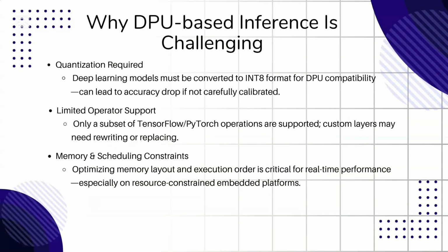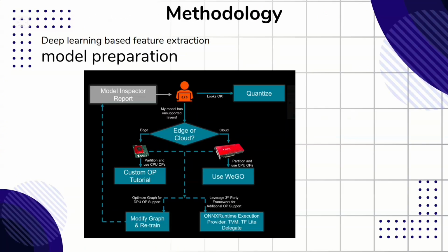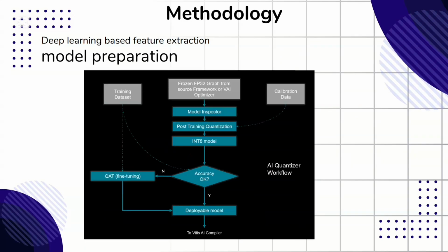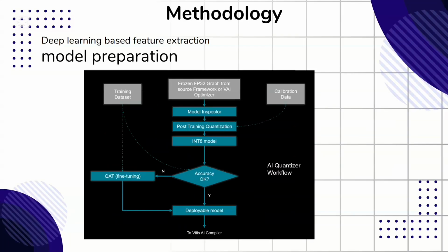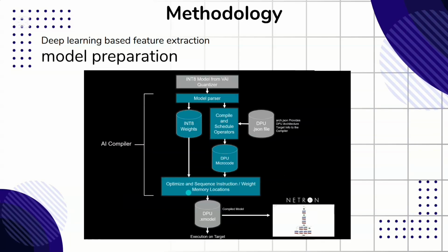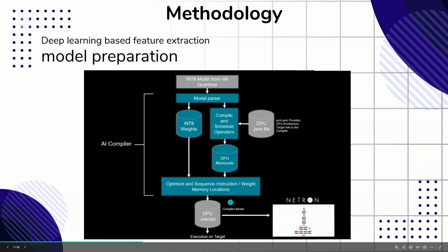With it, we compile our learned model into a deployable format called an xmodel. To do that, first we quantize our model from float 32 format to int 8 format. After that, we compile our model to be run on the DPU.